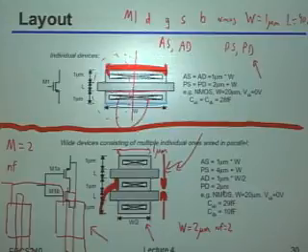Similarly, there may be times where, for whatever reason, you really can't afford to have 2 fingers like this. As an example, you need the absolute smallest transistor you can possibly build, but you still want it to somehow match. Well, then you'd have to take 2 of these things, and you probably would need the diffusion break because you have to have separate connections for the sources and drains for each of them. And then indeed, you'd again want to instantiate something that was literally an M equals 2 rather than implying some sort of drain junction sharing. It's a good question.